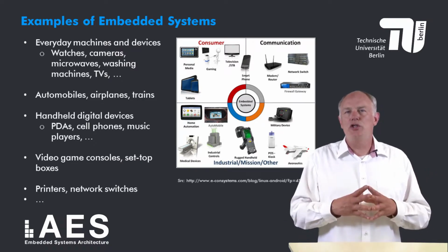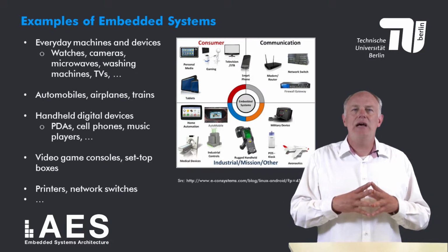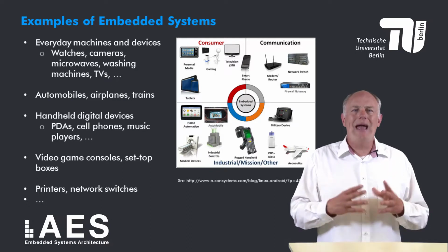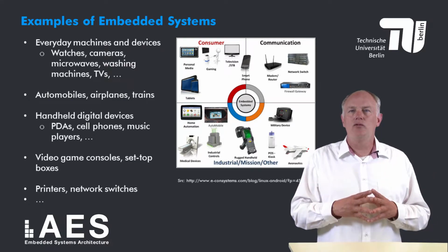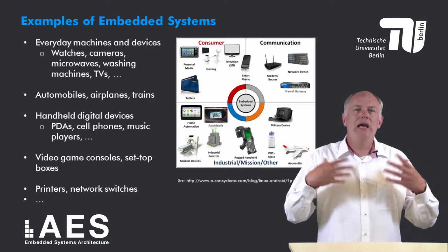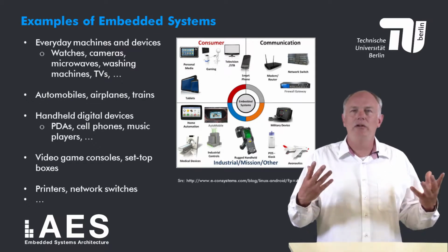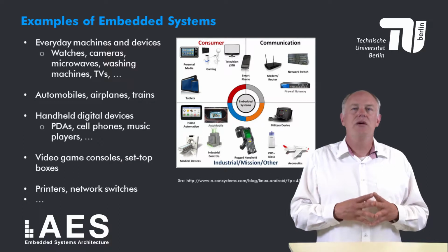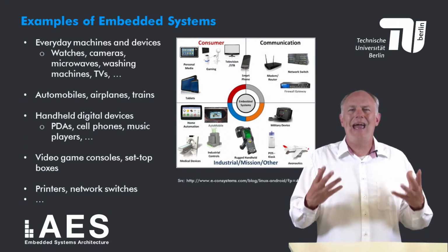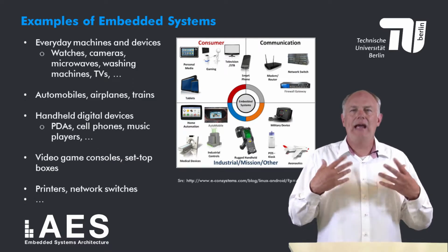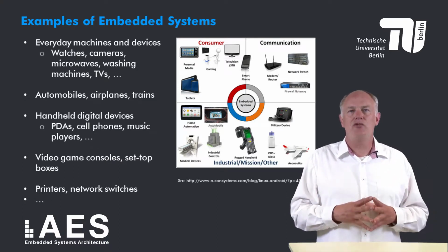What this list also shows is that embedded systems have a huge range of processing power and cost. From low-end 8 and 16-bit microcontrollers that cost less than €1, to systems containing full 32-bit microprocessors capable of processing around 500 million instructions per second and costing around €10, to systems containing high-end embedded processors that cost hundreds of euros and can execute several billions of instructions per second.